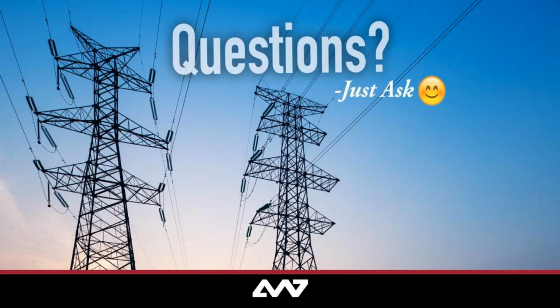So yes, it did say that. When you use TCP, typically you also open a UDP port that's used by the master for sending broadcast requests to the outstations. The outstation similarly would open a UDP port to listen for those broadcast requests. Your broadcast needs to be sent to a broadcast IP address. So this only typically works on a subnet.